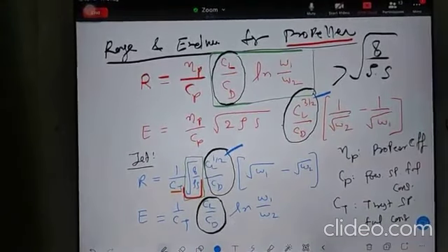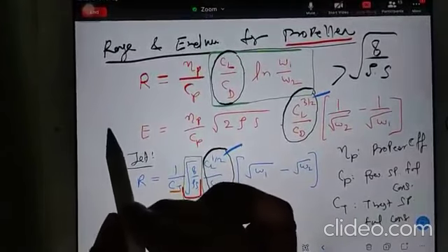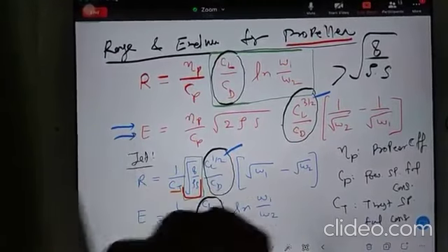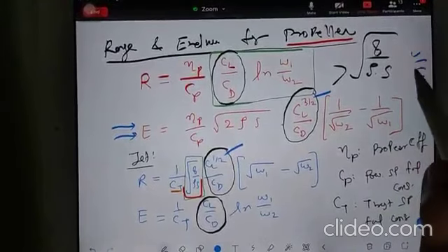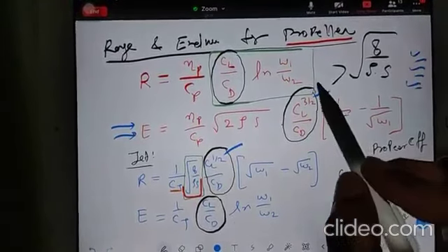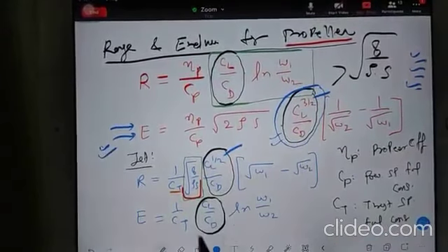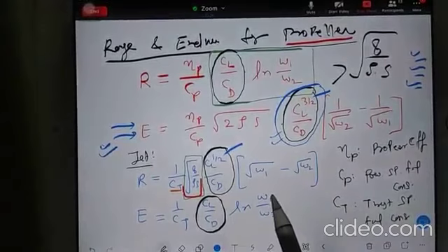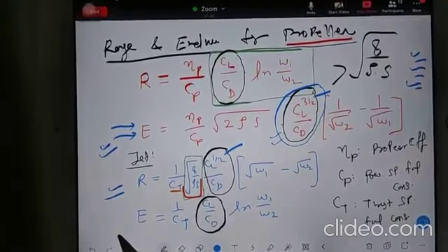Like I can ask you, the aeroplane is flying to achieve maximum endurance. Then under which condition is it flying? Minimum power, minimum drag, minimum dV. So you check this thing. This thing is maximum, then only it will be maximum. So minimum power condition. I can ask this, for example. So in that way we have to reply.